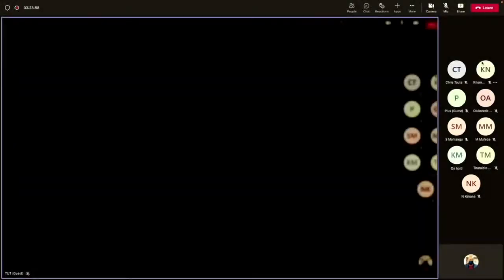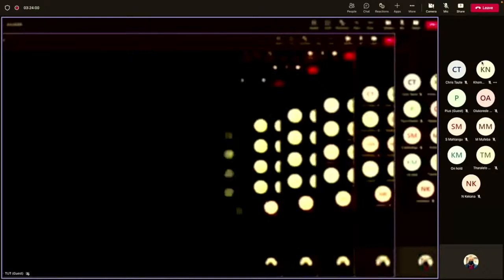As I said, everything is categorized: the substation name, the feeder name, when the incident occurred, the root cause of the fault, the customers that are fed from it, and all these columns guide the calculation of the SAIDI and the SAIFI. This is the tool that I used to collect the raw data, and I linked it to the dashboard to show the performance of the network.